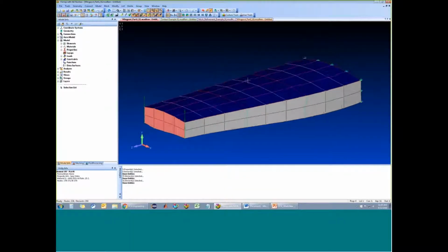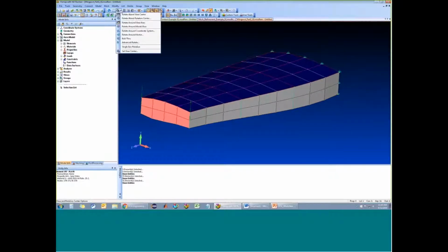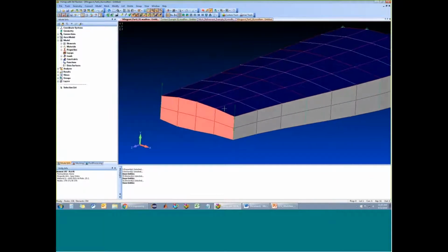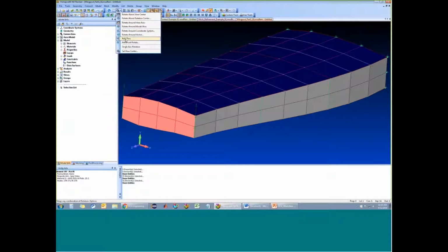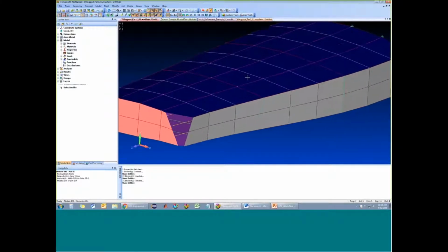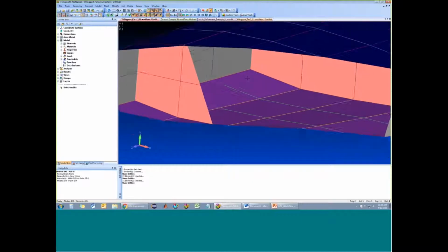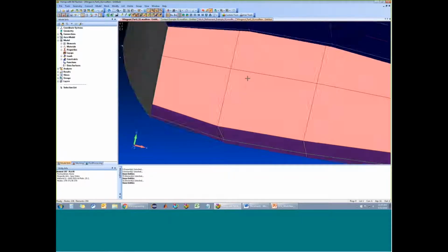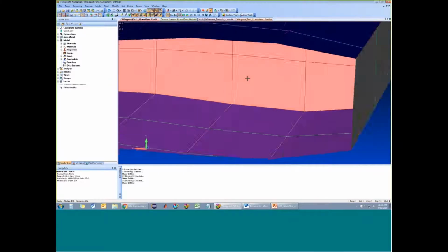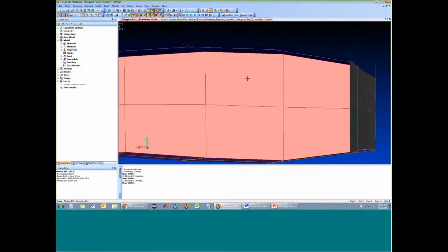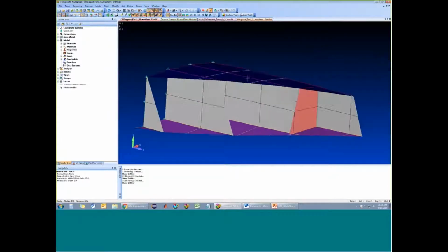Another really cool thing that they added is an option called roll through. So before, which you can get to from your view options, if I zoom in and zoom in and zoom in, that element just keeps getting bigger and bigger. I never get inside the model. I can turn on roll through, and then as I zoom in, you can see it starting to slice into that model. And I can actually go all the way inside and spin around and turn around, look at the side, look at the front, zoom back out. It's definitely a very interesting tool. So that one's kind of exciting.